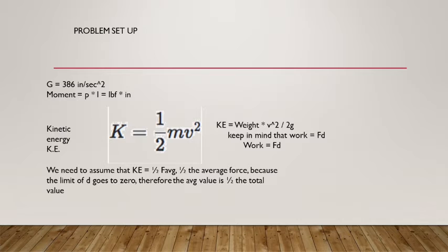So first we computed the total kinetic energy of the hammer and how that total kinetic energy is going to be imparted into potential energy, in other words, mgh. And we do our substitution. We know that there's deflection, we know there's stress, and we know the general dimensions of the wrench.